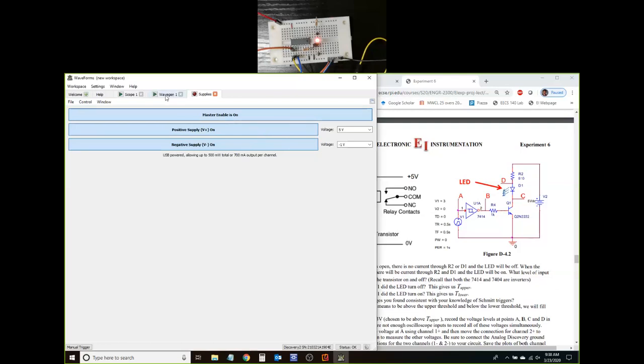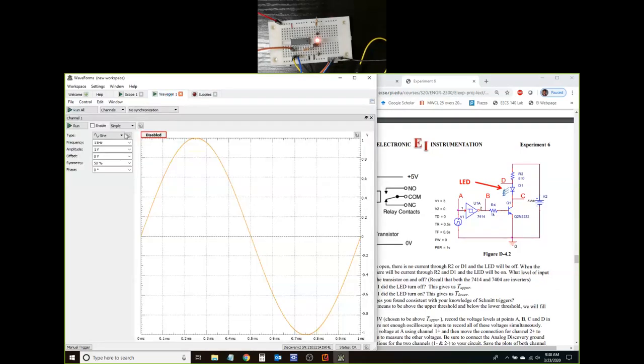Let's see, go back to wave gen, make this into a triangle wave, is going from -1 to 1 right now. I need 0 to 3. So 0 to 3 means an amplitude of 1.5. I'm going to just simply type 1.5 in there and offset it by 1.5.